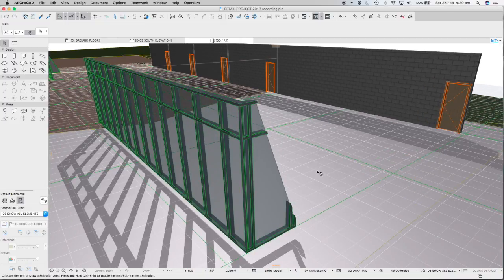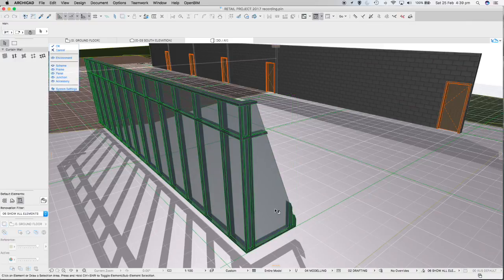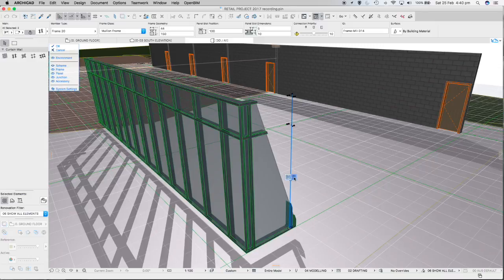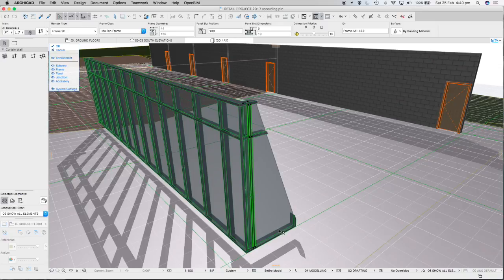I think what I will do is I'll edit, so click in here and edit, and when I hover over the top of this frame element that we've got here, and if you then click into that white selection, it'll select that frame element all the way through and press delete. So that frame element will be gone. And this one here, I'll do a similar thing too. I'll select it, but I think I'll now move it.